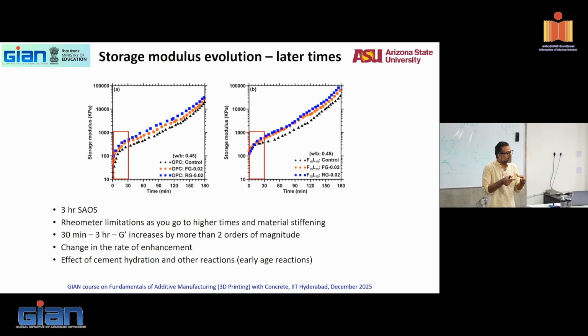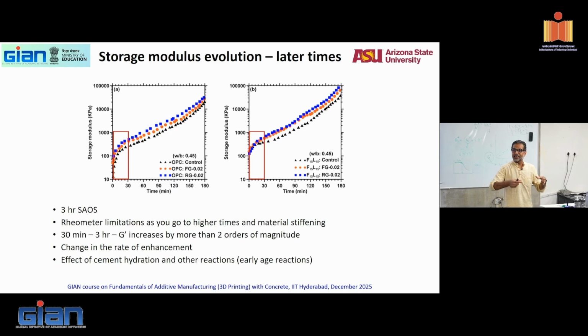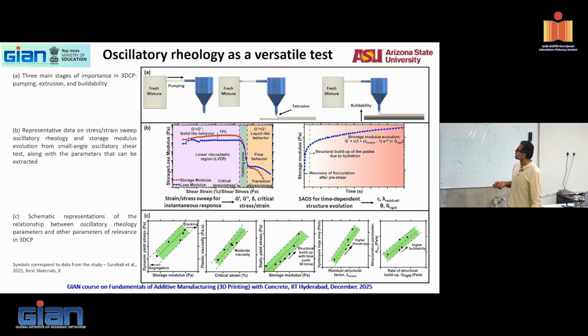So in that 2-hour gap, so you don't have to wait till the next day, in that little 2-hour gap, you have 2 orders of magnitude increase, which means you can actually play the system really well to find out when you can start building up. So this is an advantage of understanding storage modulus evolution.